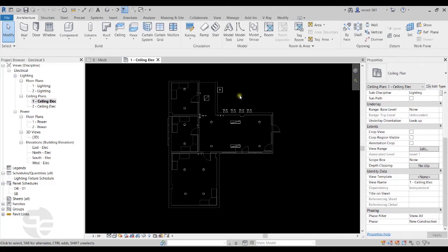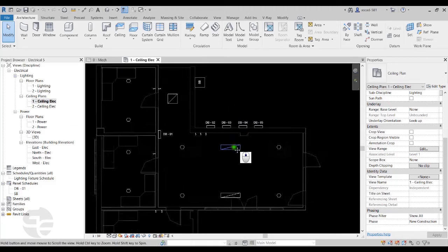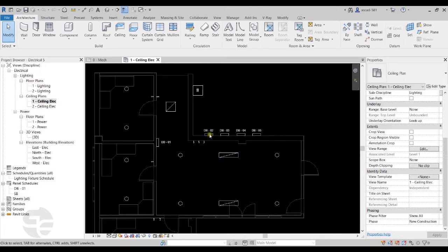So here we have an example where we need to connect these distribution boards to a switchboard. That is, we have these 5 distribution boards which are to be fed by this switchboard. In the previous versions, if we tried to connect all of them together to the switchboard with a maximum number of pole breakers as 12, we would get an error message to enable the feed through lugs option.